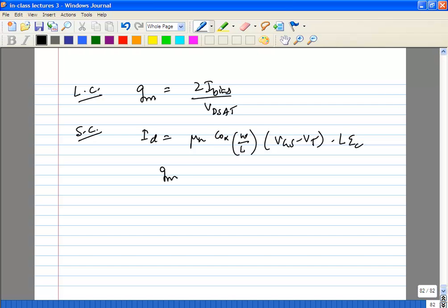So your GM is nothing but I bias over V D sat for a transistor which is completely in the short channel, right?